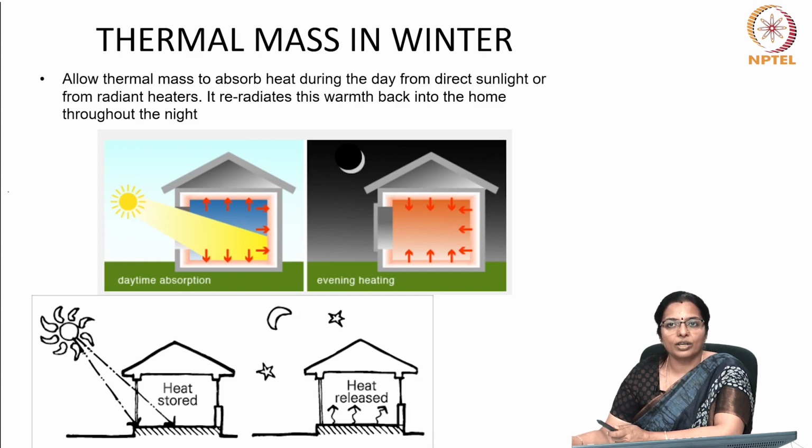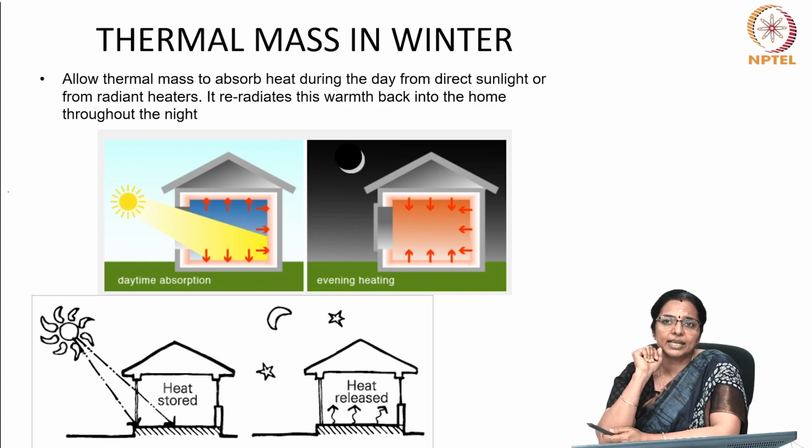In warm or hot climates where there is significant temperature variation between day and night, also called diurnal variation, heat is absorbed during the day and then released in the evening, when the excess can be either flushed out through nocturnal air ventilation, or it can be used to heat the space as the outside temperature drops. The entire process can thus be repeated the next day.